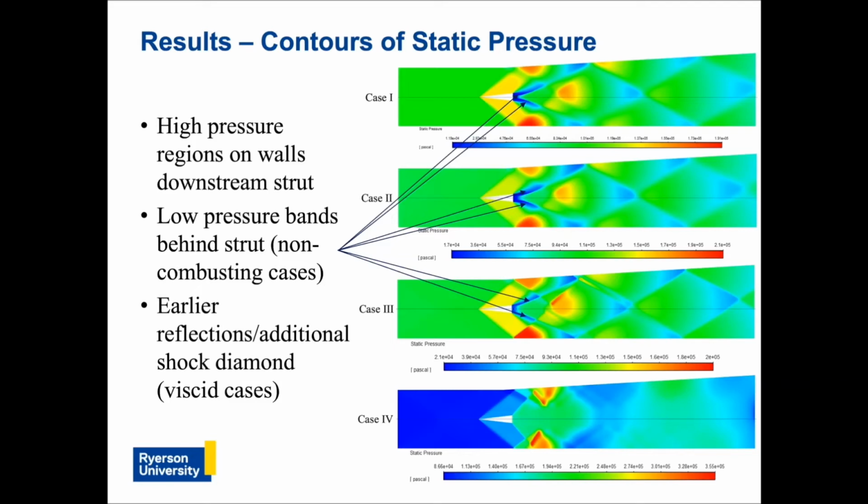This is because the expansion waves are comprised of a series of Mach waves which successively accelerate flow and decrease static properties. The additional shock reflections in cases 2 and 3 create a pressure decrease in the correlated regions. Due to the oscillating size of the combustion region in case 4, the static pressure increases and decreases with the shock and expansion interaction with the central shear layer. Since the waves travel a shorter distance between the central region and combustor walls than in other cases, the waves are weaker, so less abrupt pressure gradients occur.